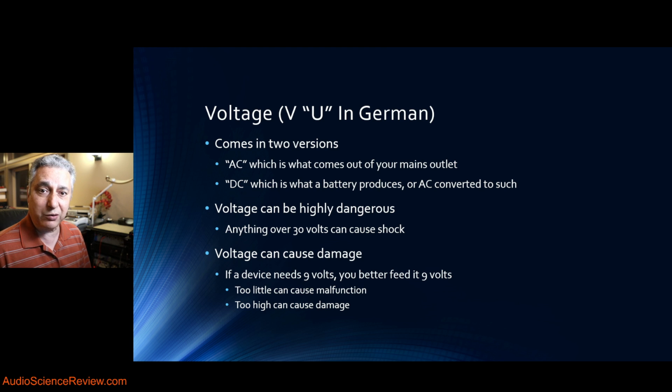One of the things I do is that whenever I have a device that becomes obsolete or broken, I may throw out the device, but I always keep their power supplies around. And when I need a power supply with the right jack, I go in the box with 100 different power supplies in there, looking for the right voltage. Current I'll address in a second, but voltage is the first thing you want to look at. And of course, if it's an adapter, you want to make sure the connector matches on that.